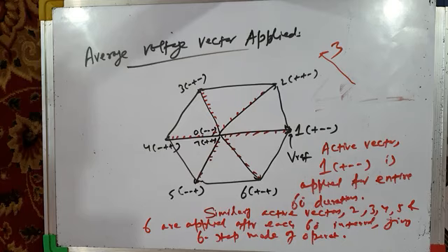So with this, I will end my today's lecture. We have studied the over-modulation of the 3-phase voltage source inverter in different over-modulation ranges. First, M greater than 1 but less than 1.15. There we found that a very low depth of over-modulation occurs and the inverter output voltage increases but not very much, and the level of distortion in the inverter output voltages is less.